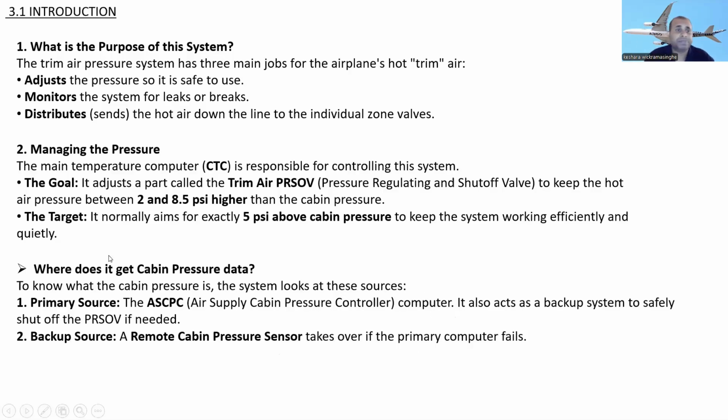So, managing the pressure. The main temperature controller computer is responsible for controlling the system. The goal is it adjusts a part called the trim air pressure regulating shut-off valve.